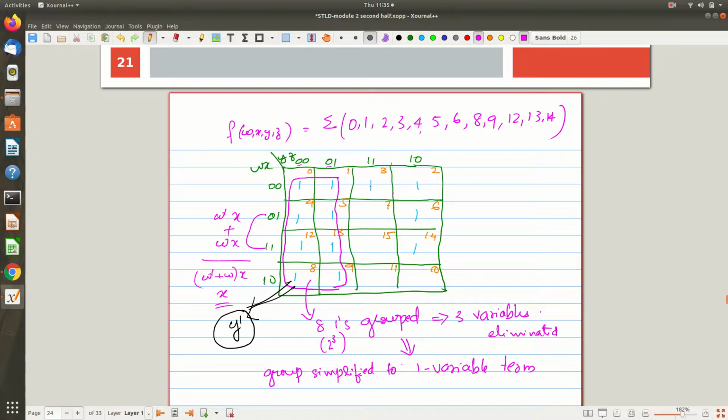These two ones you want to make the largest group, and that time you can depend on these two ones also, there is no problem. Don't think that overlapping is going to create some issue. It's not going to create any issue. In the previous examples also we saw like that, right? So we are trying to get the largest group by grouping 4 ones. If you are grouping 2 ones, further there is a chance of simplification, so keep that in mind. So always try to have the largest one, overlapping is fine, but finally at least one minterm should be covered extra, otherwise the group itself is a redundant one, that we don't want. Redundant grouping we don't want, but we need something, but more technicalities are there, we will see that.